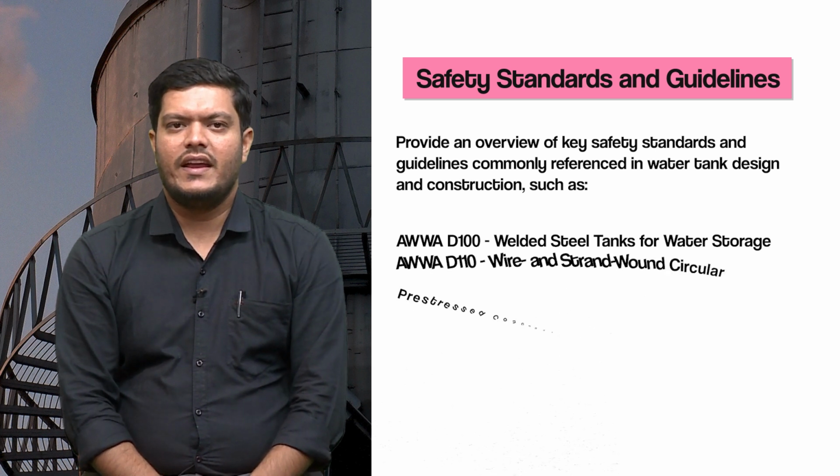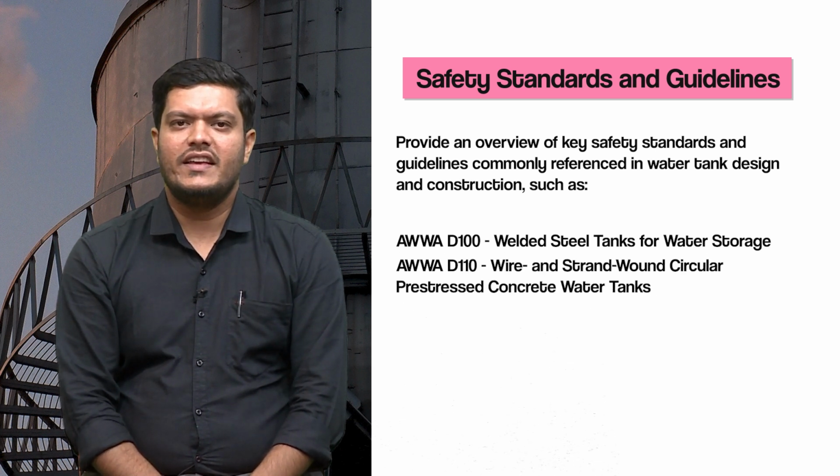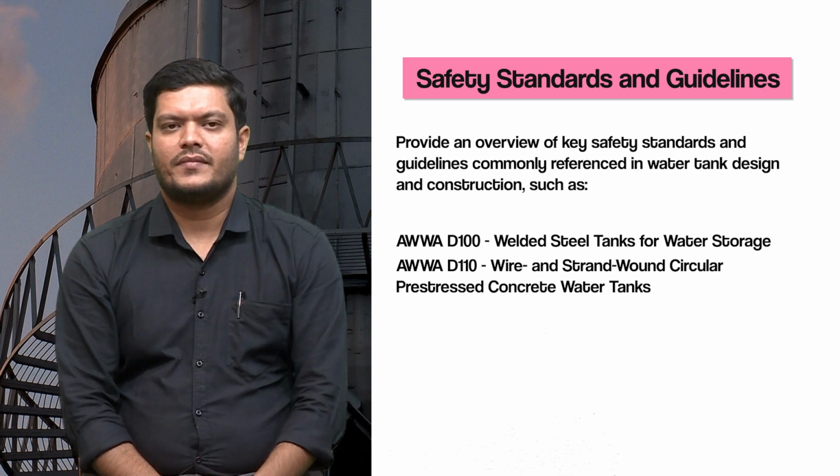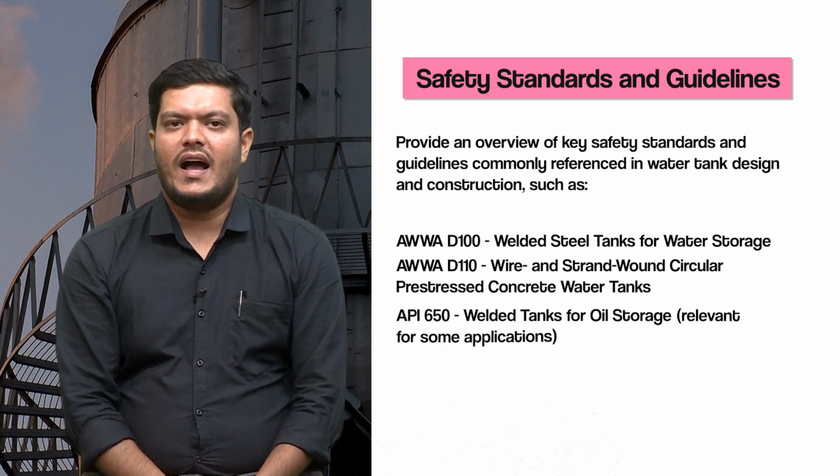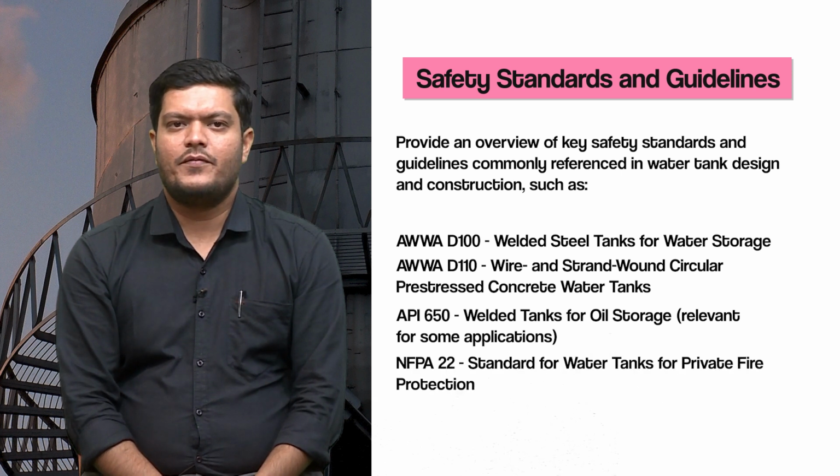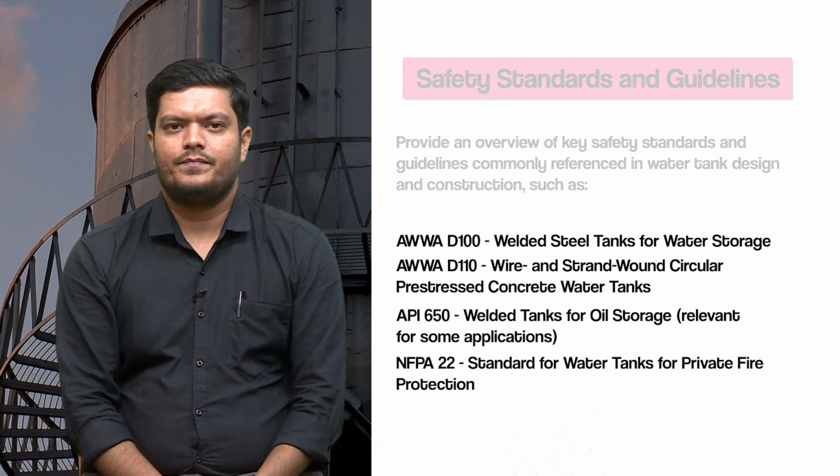Second is AWWA D110, wire and strand wound circular prestressed concrete water tanks. Third is API 650, welded tanks for oil storage, relevant for some applications. Next, NFPA 22, standard for water tanks for private fire protection.